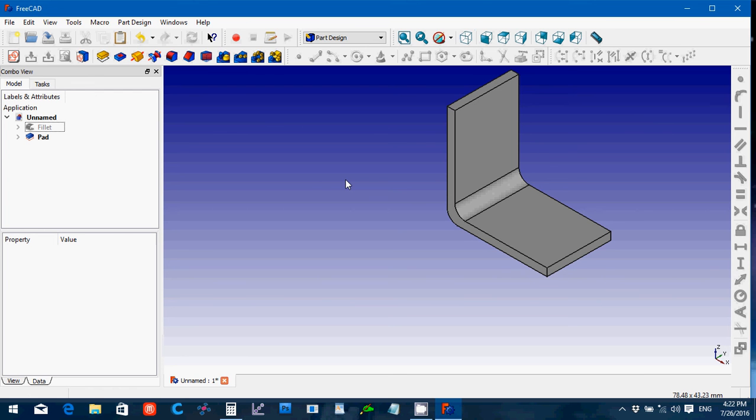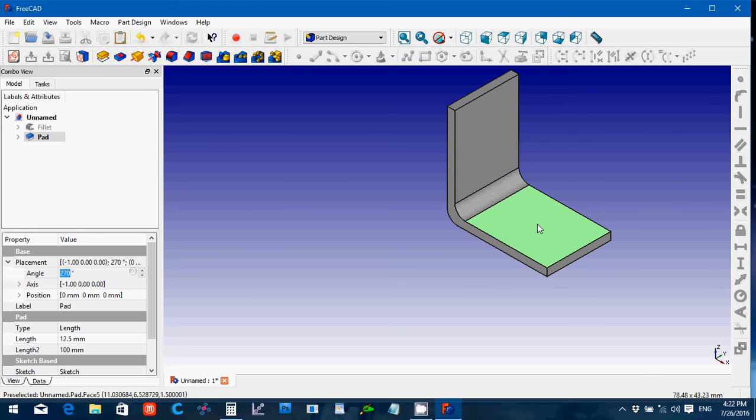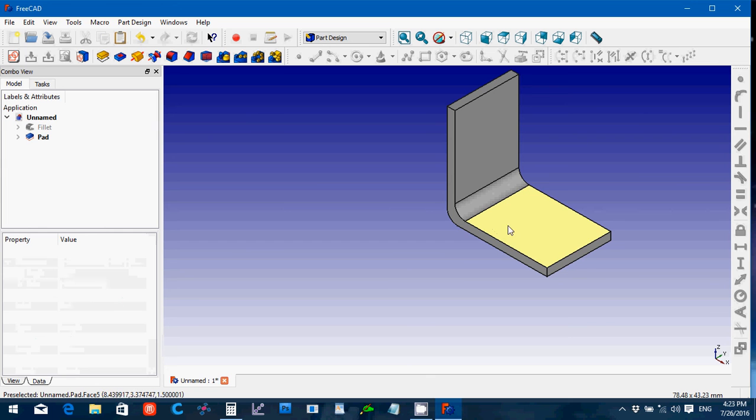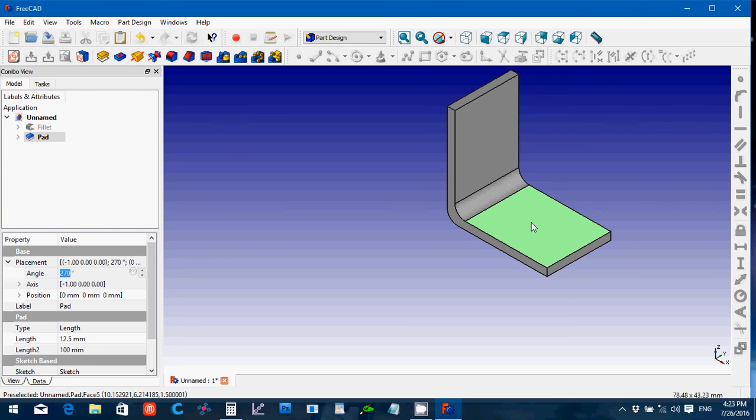In this case though, we're going to create our holes the same size as the smaller hole. So we're going to do the 4.5 millimeter holes and it's so I'm selecting this one first, that face. We want that face.